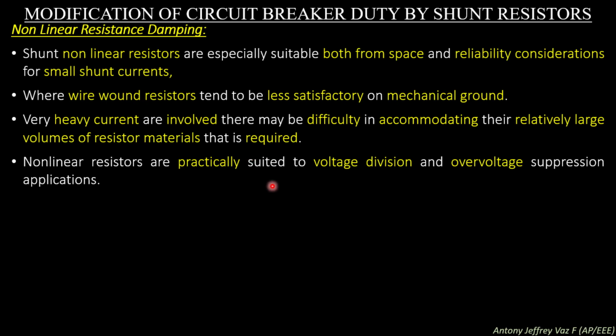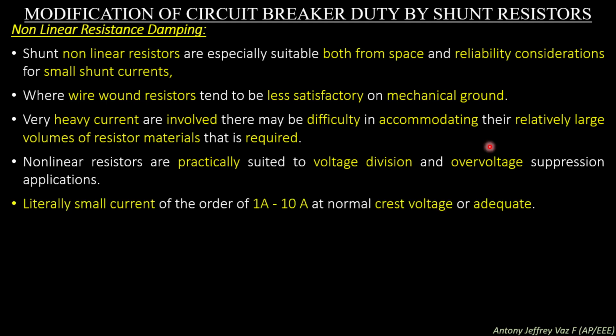Non-linear resistors are practically suited to voltage division and overvoltage suppression applications. So while using them in practical applications, nonlinear resistors are suited for voltage division and overvoltage suppression. Typically, small currents of the order of 1 ampere to 10 amperes at a normal crest voltage are adequate.